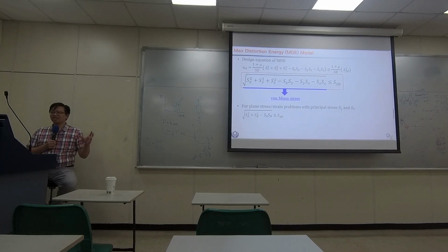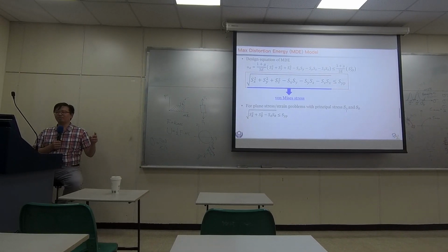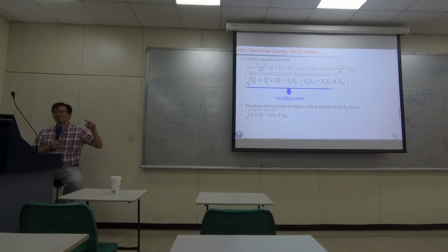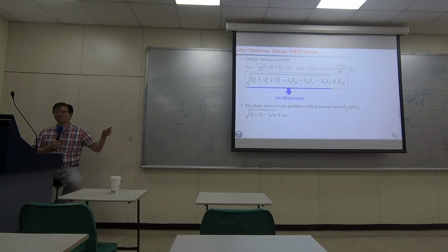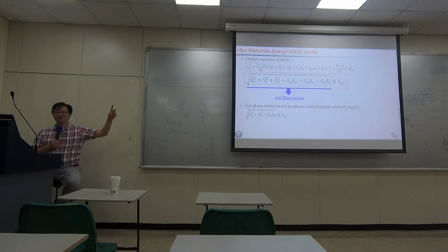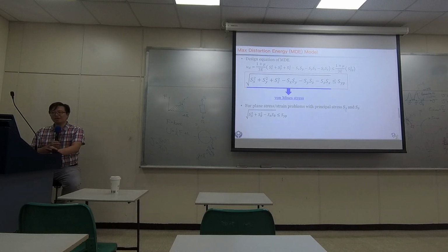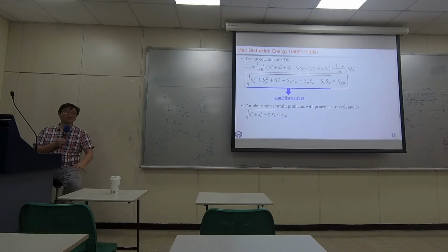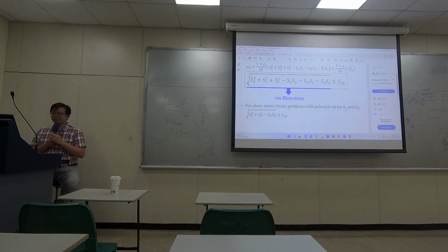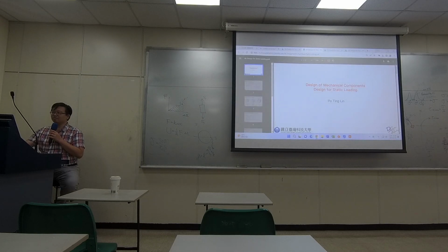It's a stress that can be computed from the principal stresses along all three directions. So von Mises stress is like an equivalent stress. So if you have some stress along x or y or z, your von Mises stress will be larger. But it's an overall stress behavior along all three directions. So von Mises stress has no direction. If you go to the internet and Google, let me show you.